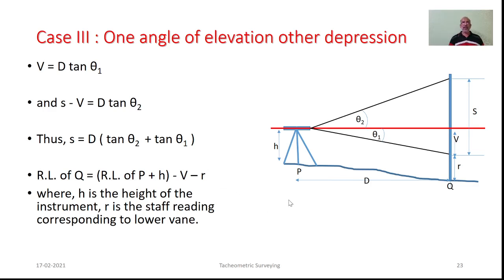So the way you see here, the method is totally based on working out the staff intercept and the vertical angle measures read by theodolite as θ1 and θ2. Calculations are very simple and give reasonably good results for given circumstances in order to determine the elevation of the stations, which are placed at quite a height wherein ordinary leveling cannot be employed.